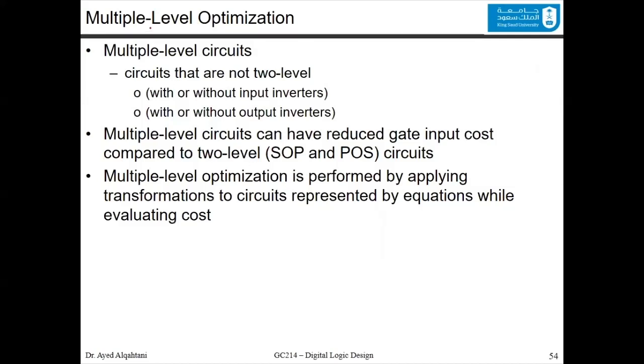After we see some of these gates now, the first gate being the XOR and XNOR, and the second gate being the tri-state buffer. Now, the tri-state buffer, we show it in this set of slides because it shows you a simple and easy design for circuits that even have a third output, which is the high impedance.